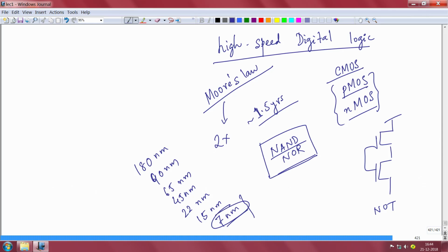Of course, this is also a business game. What these dimensions mean: initially they meant maybe the size or the gate length of the transistor, but now essentially it means the distance between 2 adjacent lines, the resolution in a way, you can say 7 nanometer. But please remember that 7 nanometer for Intel and 7 nanometer for Samsung will not be the same. These companies have different terminologies nowadays. So for example, 7 nanometer of TSMC might actually be 10 nanometer of Intel and so on.